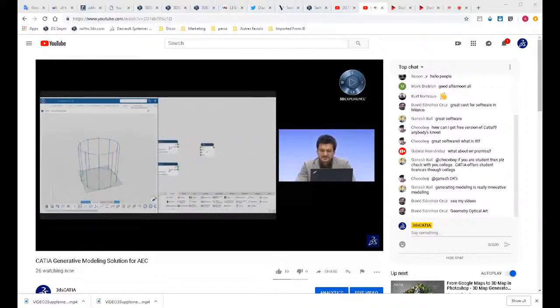Going a little bit further on this logic of embedding intelligence into the features, I am going to show you how you can influence outputs and inputs without creating new features. As an output of my dividing point feature, I've got a list of points. So I have one list of 10 elements, which are points, and I'm going to influence this list with a list management operator, because I want to change the list structure.